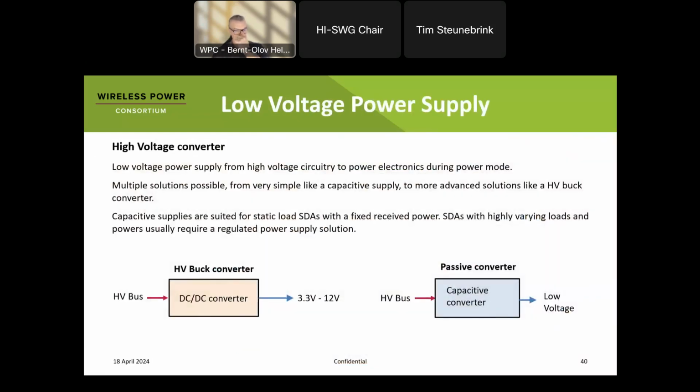DC-DC converters, as I said, are sometimes a challenge because it's 1% duty cycle in the pulse width modulation. That means that we don't have much use of traditional converters out there. It needs to be quite a good design to get 1%. Usually DC-DC converters are considering like 50 or 70%. So you need to have a dedicated high voltage converter.